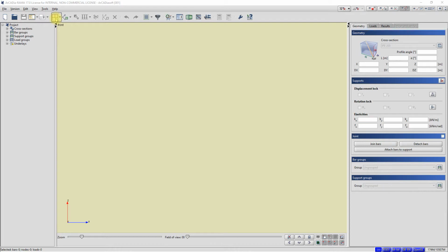The operating mode button is an expandable button because it is located next to the button with a triangular marker. I click the left mouse button on the expansion marker and display a list of available options. I have two options to choose from: plane free and spatial between nodes. I will choose the plane free mode. I click the left mouse button on the plane free option. The mode of operation has been selected.